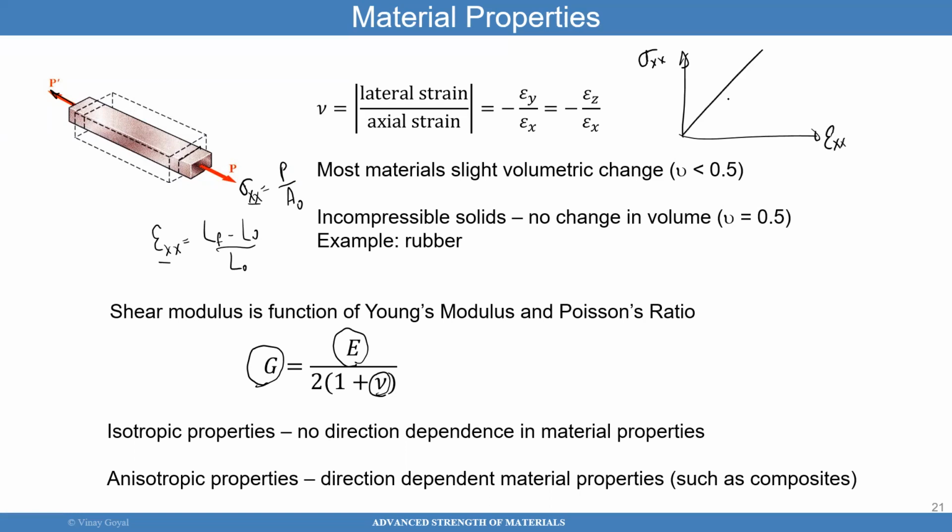And that gives me a slope. That's your modulus. But the coolest thing is I can also put a strain gauge going in the y direction, and I can plot that too. I can then take the ratio of epsilon YY to epsilon XX to get the Poisson ratio. Okay, great. Then I can do another test, and in that test I'll apply a torsional load.